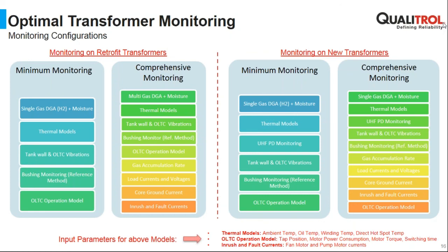And the other question, if bushing monitoring is used for that, then it needs to be protected for over voltages and fast transients, which most of the systems are today. So I don't see any big issue, because usually you have the protection in the sensors you are screwing directly to the bushing tap.